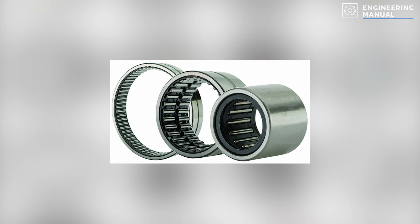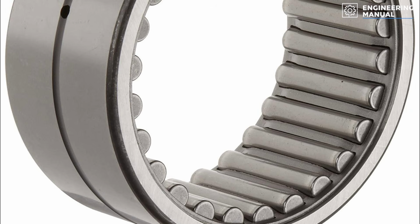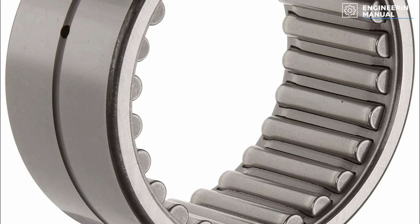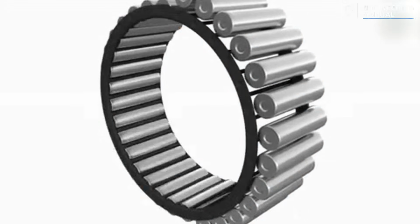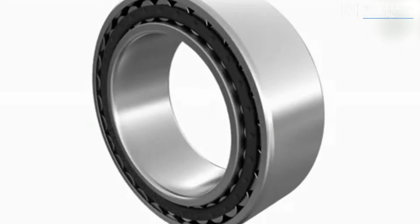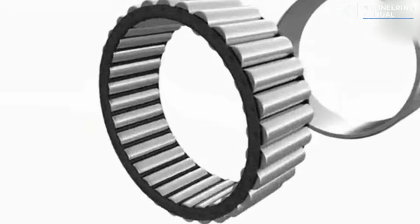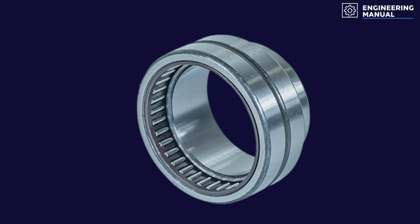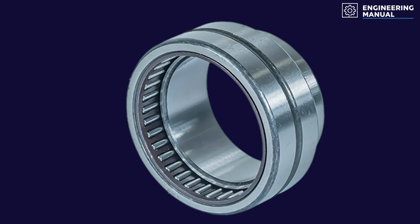Many designs eliminate the inner race entirely. The rollers run directly on the shaft itself. That saves even more space. But now the shaft must also function as a precision bearing surface. Its hardness, surface finish, roundness, heat treatment. None of those properties are optional anymore. The shaft has become part of the bearing.